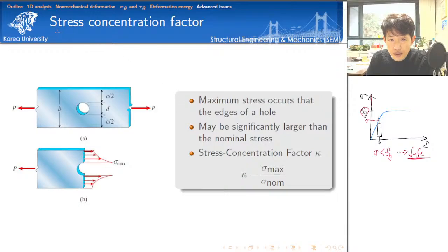And then the third one is the stress concentration factor. In Korean, 응력 집중 계수. Okay, in our discussion, even if we have a hole, we just consider the net area, for example, to calculate the stress value. We divide the load by the net area, A net, isn't it right? So A net, that's what we did.